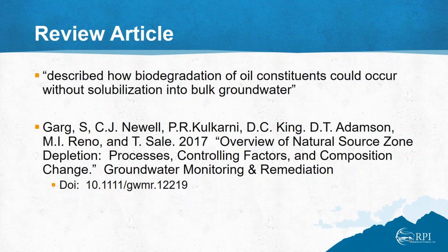Another question has to do with electron acceptors. And we know there's an awful lot of mass in these LNAPL sites, so it takes a lot of electron acceptor in order to deal with that mass. So the question was, how do I get more electron acceptors into the subsurface when the original amount of acceptor is used up? And we actually can do that in a couple of different ways.